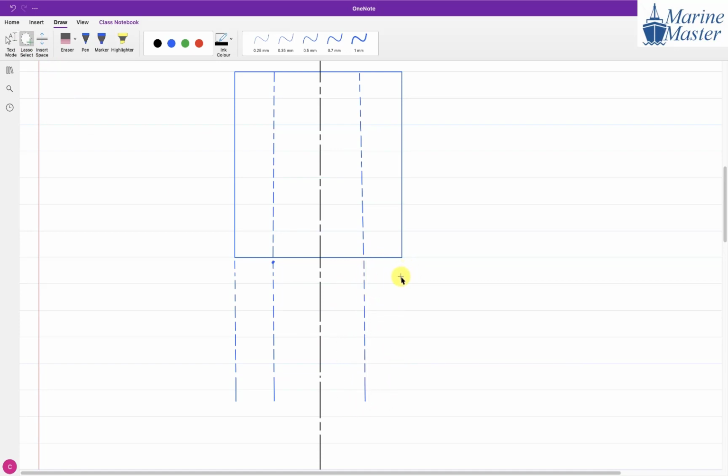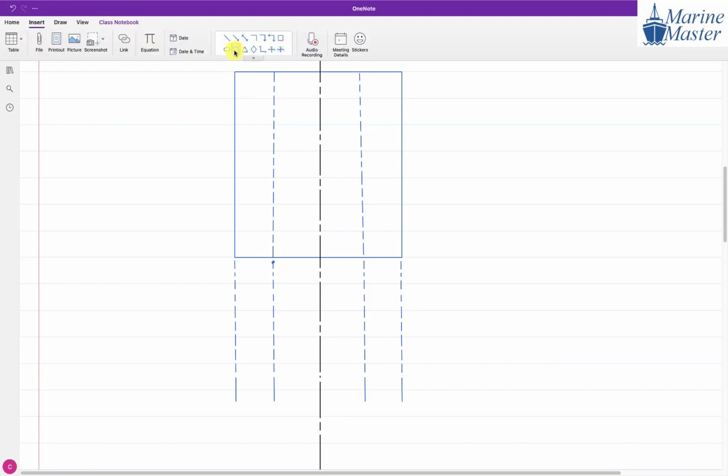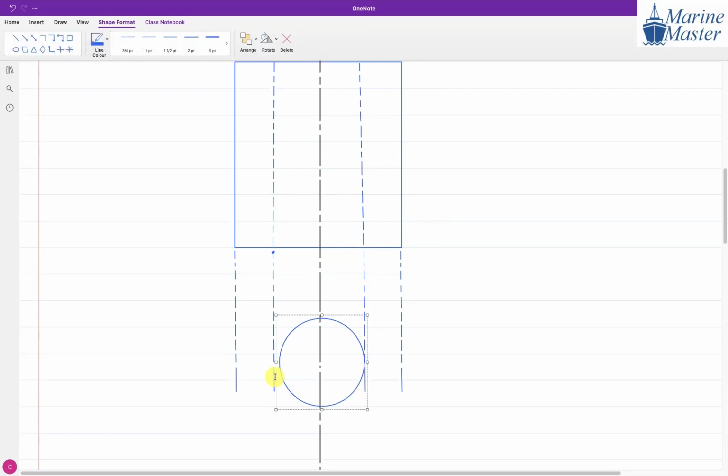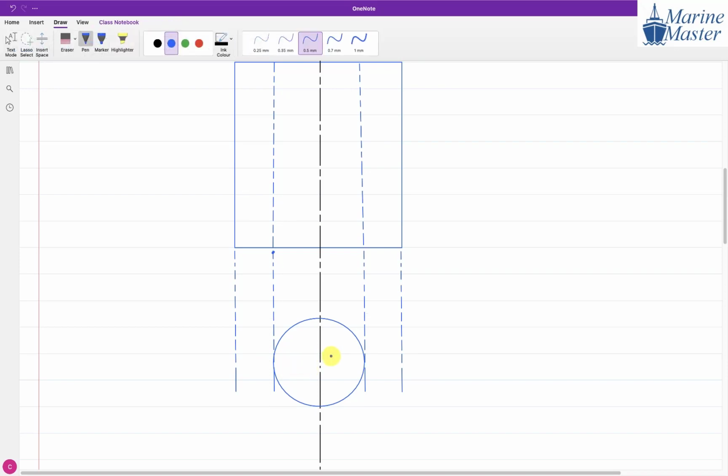And here another dotted line. The purpose of this dotted line is to show the cross section. And what cross section will we have here, everyone? Circular, hollow circular. So observe, guys, an important suggestion from my side: if you have to draw this one, first of all always draw the cross section and then from the cross section draw that one.